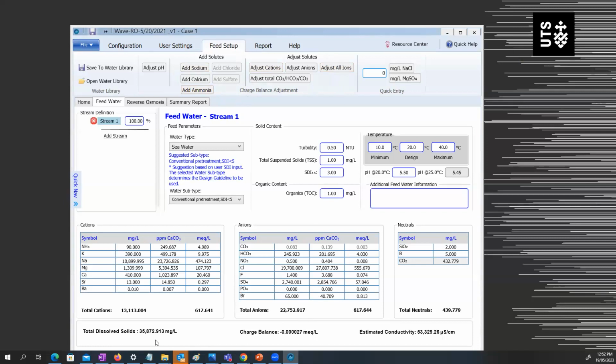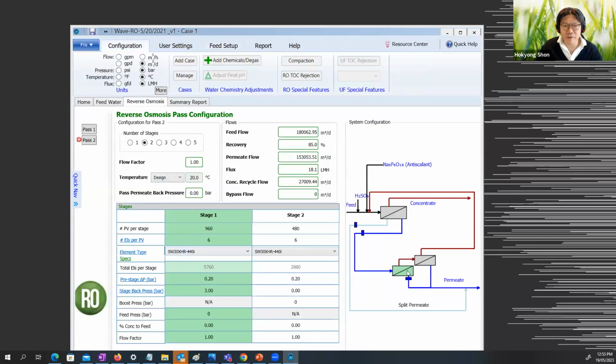Professor, another thing: the temperature we input is between 13 and 20 or something like that, right? And we adjust pH accordingly. We click on adjust pH, and it gives around 5.5. This 5.5 is from your pretreatment adjustment, which your RO membrane receives, but you can change the pH in your system, let's say pass one, pass two.